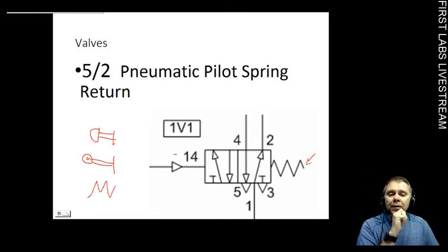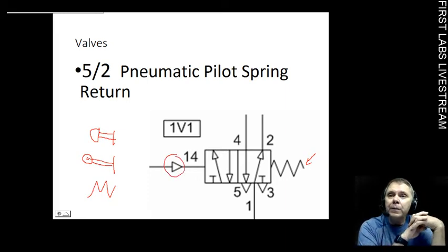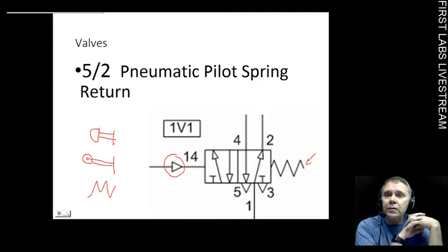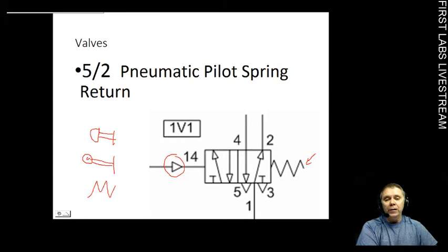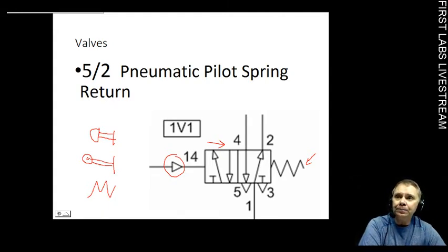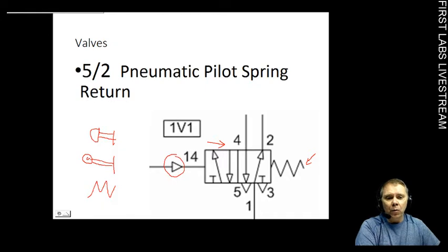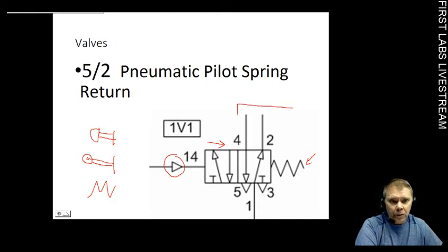This valve is being operated by air. So you can have valves being operated by other air circuits, which is very convenient. In this case, when you operate this valve here, the whole valve will push to the right. It can push itself to the right. And right now, you can see that port 1 is connected up to port 2. So again, you might have it in a double acting cylinder like this. There's a port here and a port there.